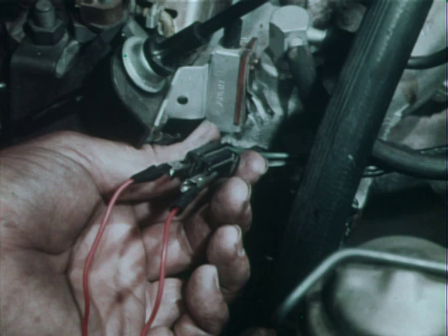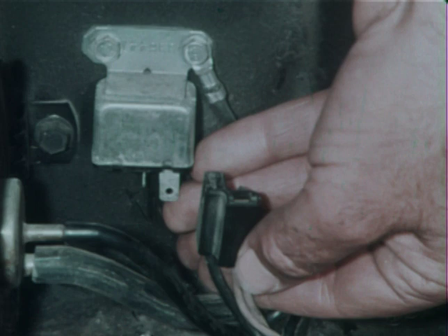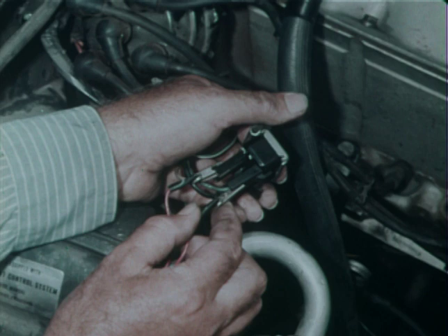However, since he is working on a 1974 Vega, the technician next tests the throttle cutoff switch in the same manner as he tested the thermostatic switch. The clutch does not engage, indicating the switch is not the problem. He then tests the time delay relay by removing its electrical connector. If all other components are functioning properly, the clutch should engage when this connector is removed. Here, the clutch does not engage, so the technician reinstalls the connector and proceeds to the AC relay.